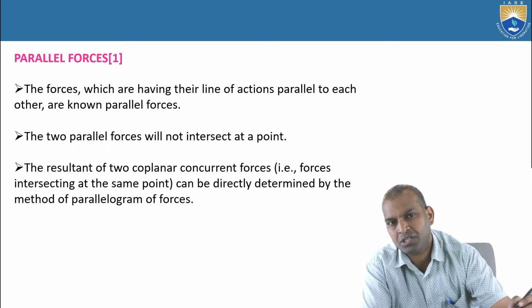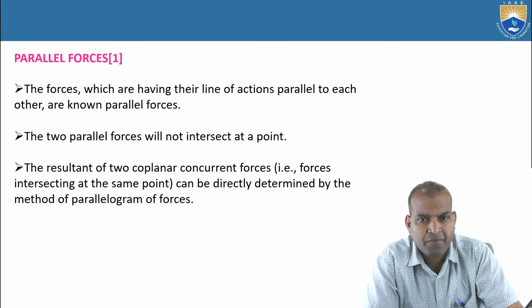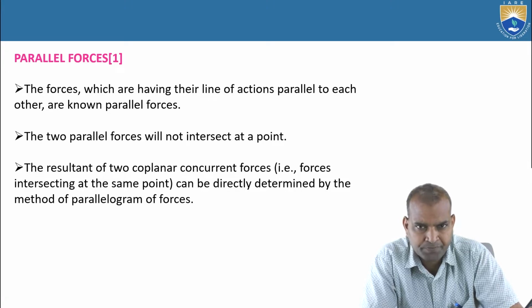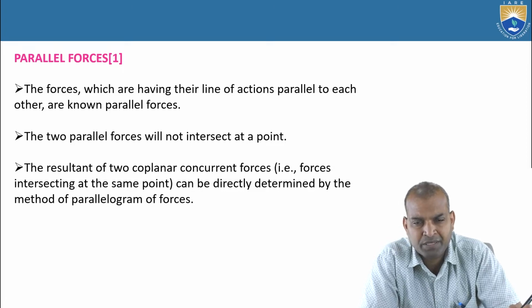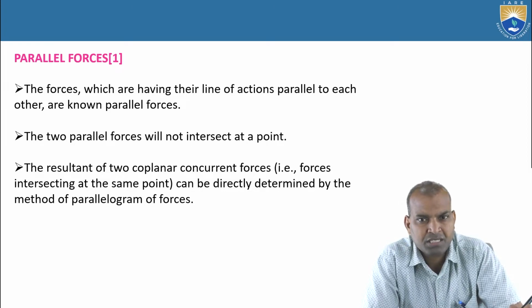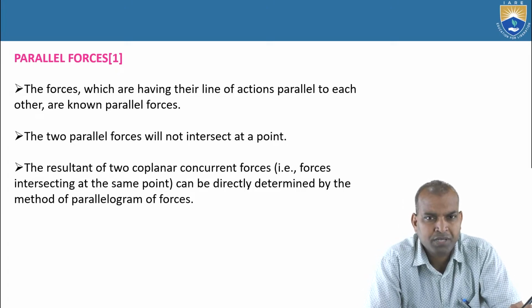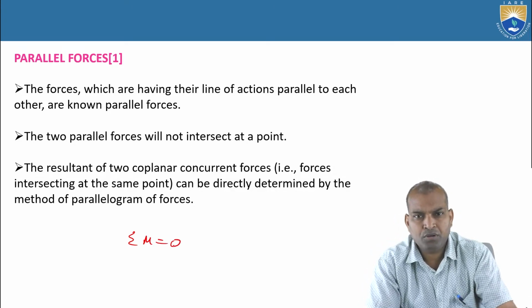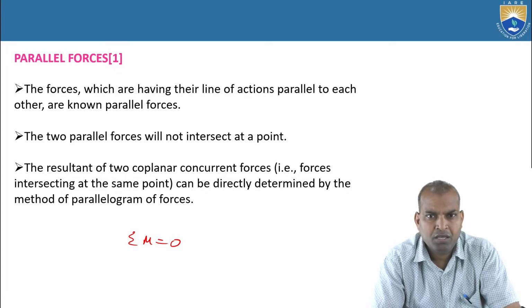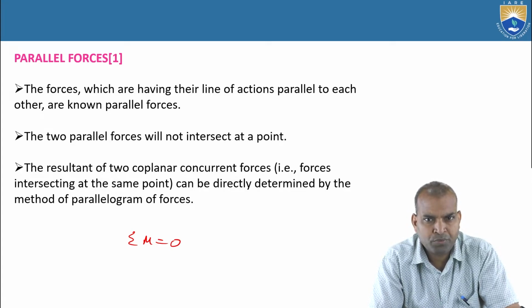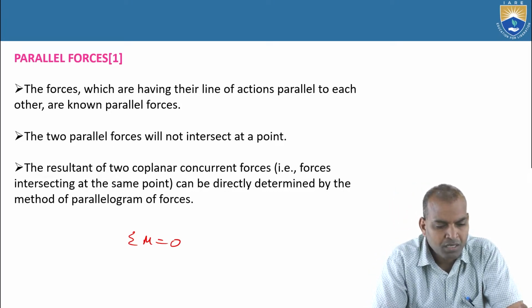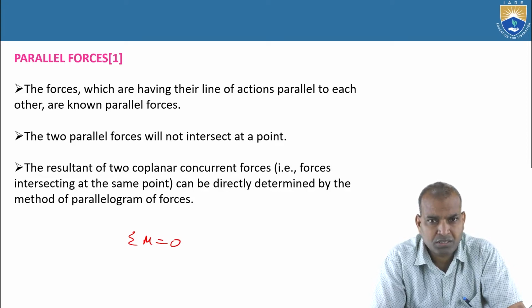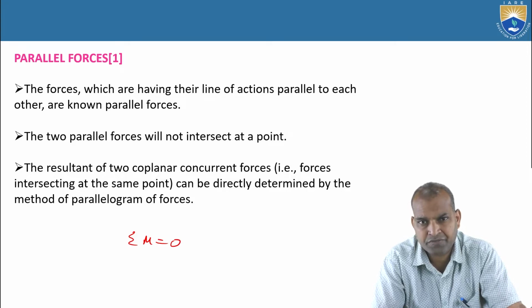In this session, we are going to study the moment of a force, which comes into the picture when parallel forces are acting on a system and we want the body to be in equilibrium momentarily. That is called moment equilibrium. We will apply the moment equilibrium equation, sigma M equal to 0. What is sigma M equal to 0? The algebraic sum of all moments about an arbitrary point equals 0. There are two types of moments, as we studied in previous sessions: one is clockwise moment, and another is anti-clockwise moment.